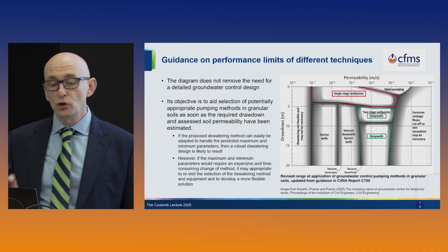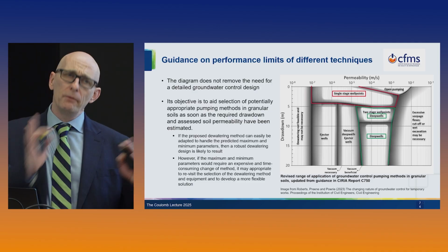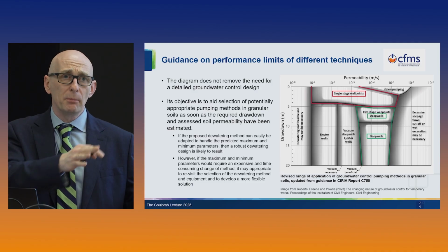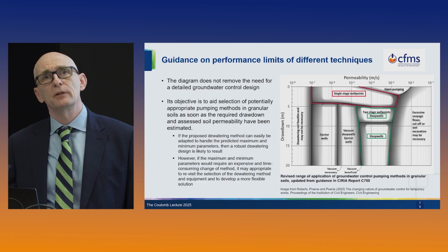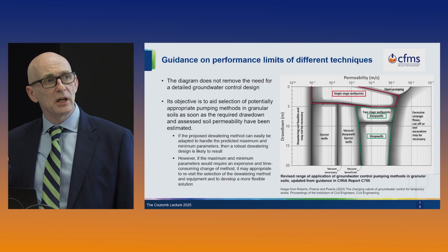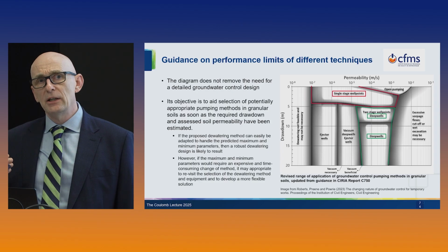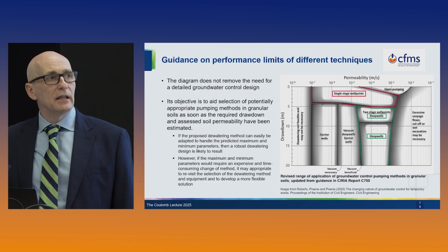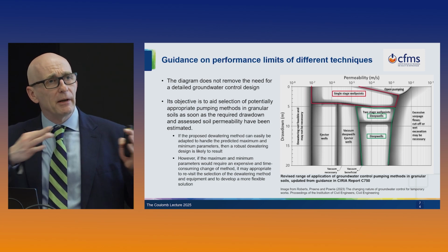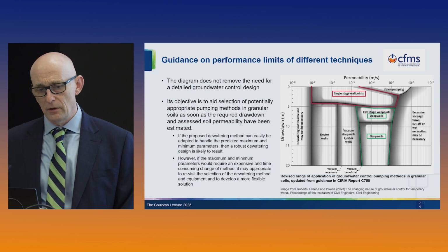Now, there are other diagrams available in other publications, this is one I'm familiar with. These diagrams do not remove the need for a detailed ground control design, but the objective is that they let you, at a very early stage of a design, identify the most likely forms of ground control methods, and that can help you direct your design and direct your investigation further.